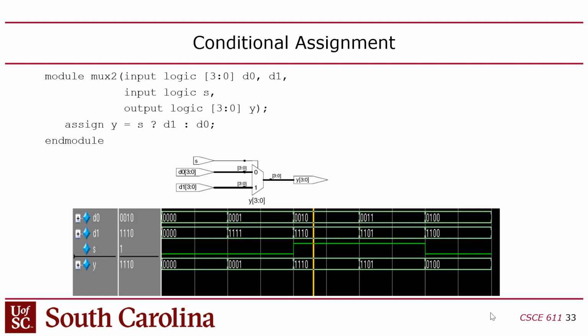So multiplexers show up a lot in your design, and they're nice because you can just write essentially one expression, which the synthesizer will then interpret as being a multiplexer. So even if you have a structural design where you have a register file and a control unit and an ALU and all these big abstract blocks, you still will mix in these little multiplexers into the structural code just to take care of fan-ins, because remember, each signal can only be driven by one driver, so if you need to be able to get multiple sources into a place, you've got to use a multiplexer for that. That's how fan-ins are done, is with multiplexers, right?